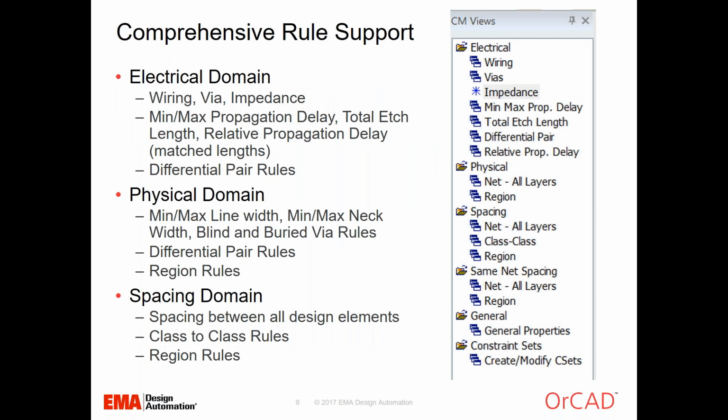Cross-probing between CM for OrCAD and the schematic canvas is also available, which makes selecting nets for constraint assignment very easy. CM for OrCAD supports a set of comprehensive rules. This includes physical, spacing, and electrical constraints.